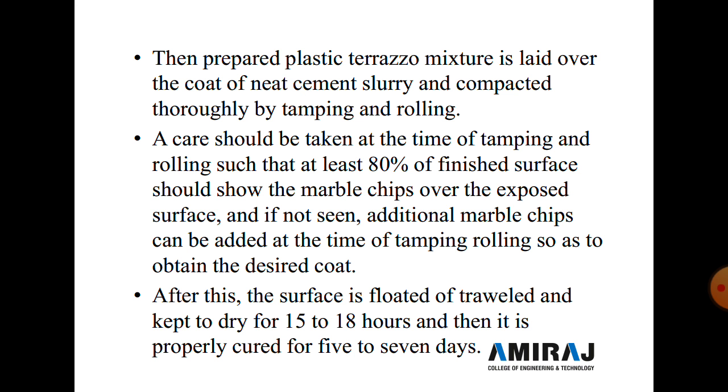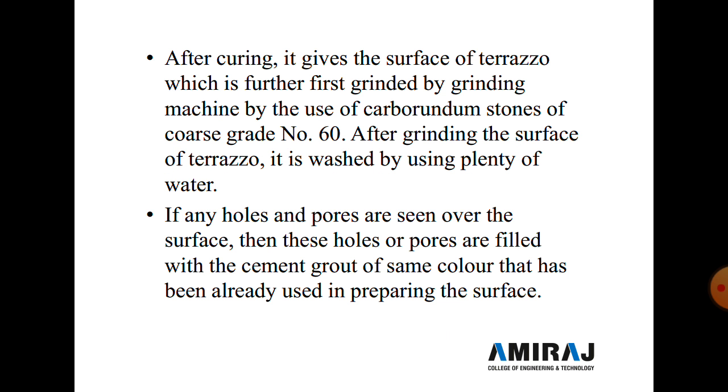It is kept to dry for 15 to 18 hours, and then it is properly cured for 5 to 7 days. After curing, it gives the surface of terrazzo, which is further ground by a grinding machine using a carborundum stone of coarse grade number 16, and after grinding, the surface of terrazzo is washed using plenty of water.